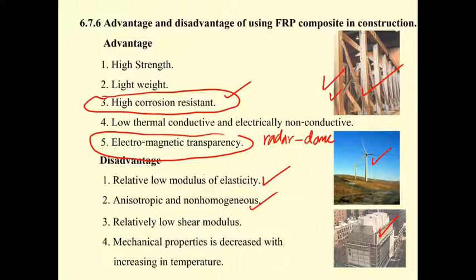And low shear modulus, that means the total deflection will come from the deflection due to the moment plus the deflection due to the shear. When the temperature increases, the mechanical property of this material decreases.